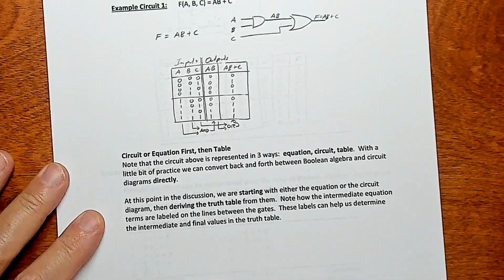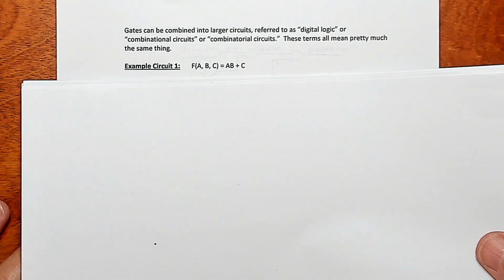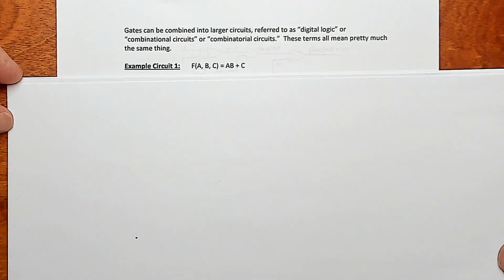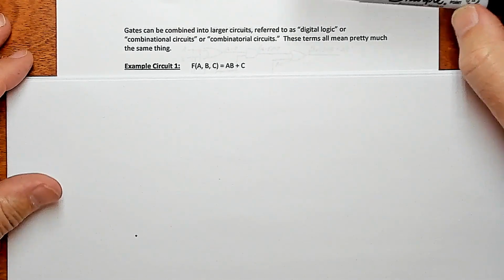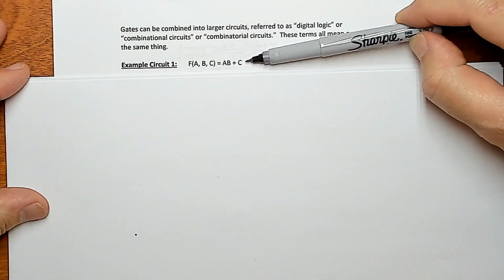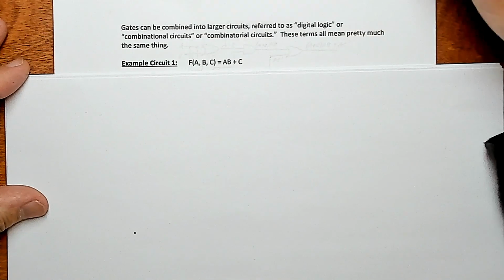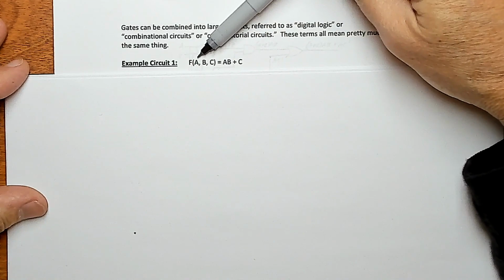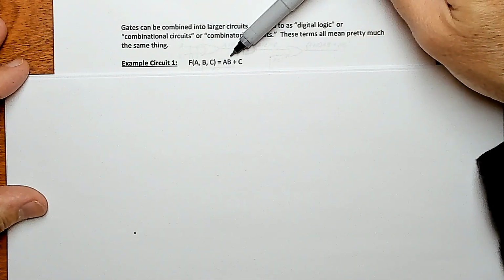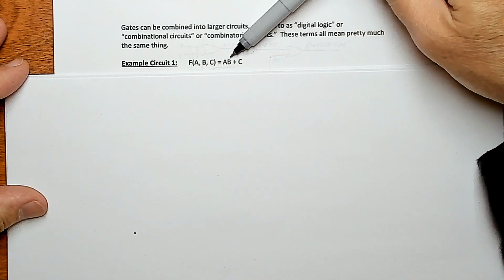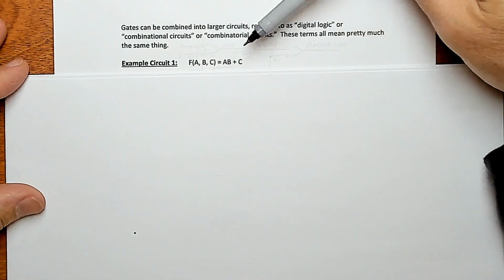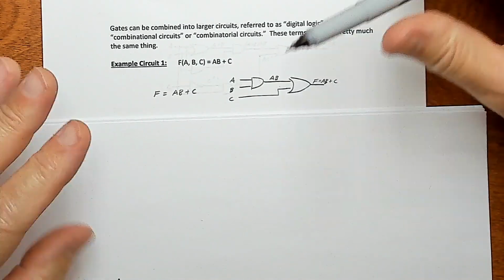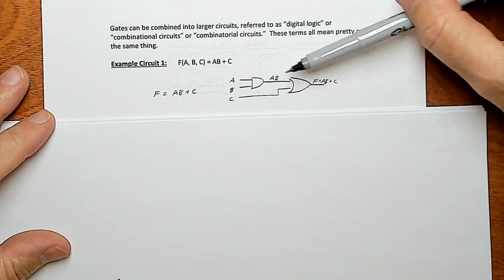So now that we have these three gates defined, we can combine them in different ways and get what are essentially digital circuits. It's just that sometimes those circuits are represented in different ways. So here we could have this, an arbitrary combination of operations. We have a function f with inputs a, b, and c, and we're ANDing a and b, and then taking that result, because ab has precedence, and ORing that with c. So we could represent it algebraically like this.